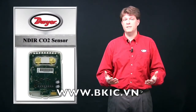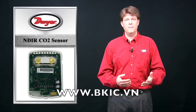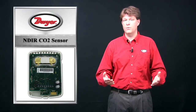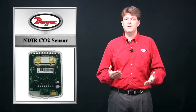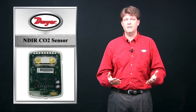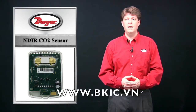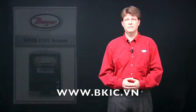There are two basic types of sensing technologies, chemical reaction and infrared spectroscopic. Most chemical reaction sensors are electrochemical sensors which are not as reliable as they can interact with multiple gases and wear from interaction with the gas. Non-dispersive infrared sensors, often called NDIR, deliver high accuracy and fast response time. NDIR sensors have no contact with the gas, making them more reliable, and are constructed for specific gases so that they aren't affected by other gases. NDIR sensors are the most reliable method for detecting carbon dioxide gas.